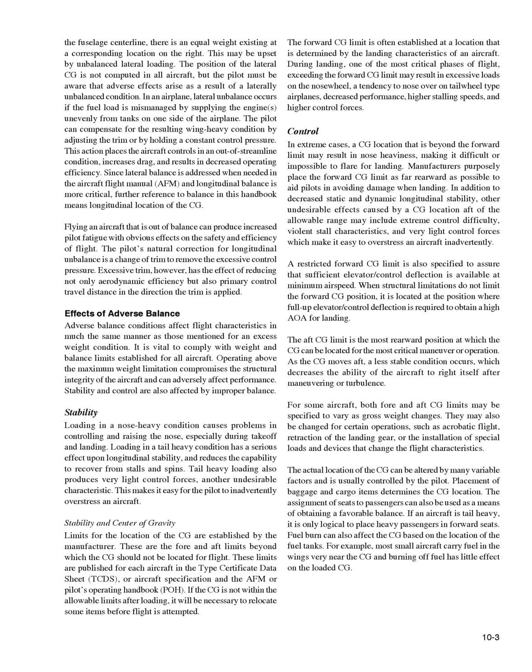Stability and center of gravity limits for the location of the CG are established by the manufacturer. These are the fore and aft limits beyond which the CG should not be located for flight. These limits are published for each aircraft in the Type Certificate Data Sheet, TCDS, or Aircraft Specification, and the AFM or Pilot's Operating Handbook, POH. If the CG is not within the allowable limits after loading, it will be necessary to relocate some items before flight is attempted.